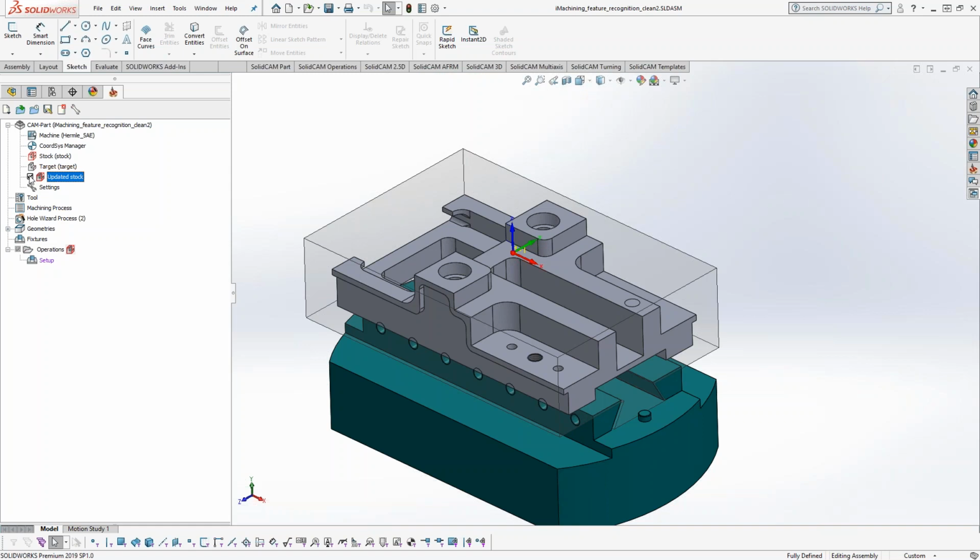Usually we are deciding, okay, I want to cut this face first and then this face, and we're trying to figure out the order of our machining operations. In that context, we're also trying to decide what tools we're cutting. And then as we program along, we go to the simulation, we see what the toolpath looks like, we see how everything is going, we make changes. So the entire time, machining is very, I would call it, artsy. Each programmer finds their own way.